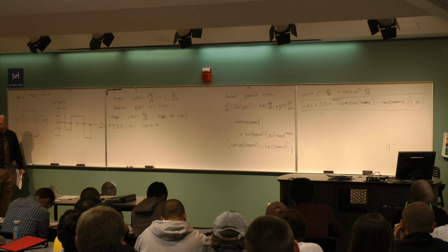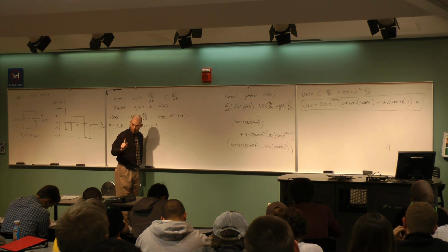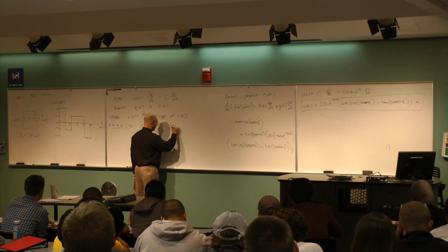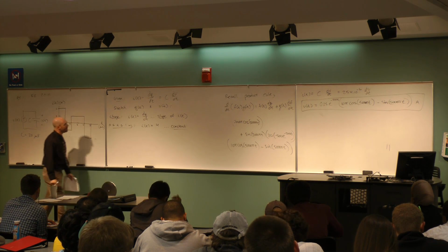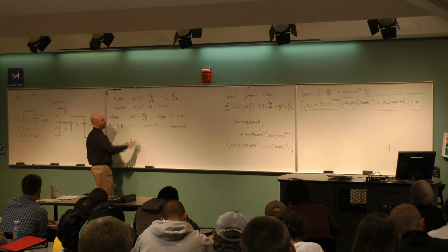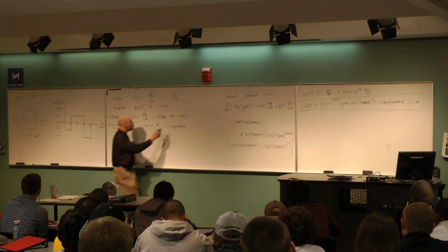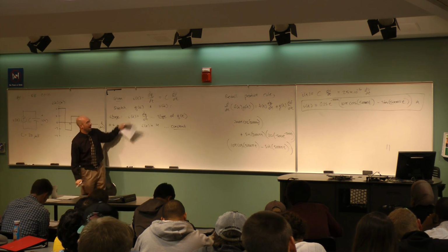What kind of function is 4 amps? It's a constant function, so it's constant throughout the interval. It's not just that value at one point, it's over the whole interval. So if that's a constant, then that is the slope of Q. The slope of Q is what i is.